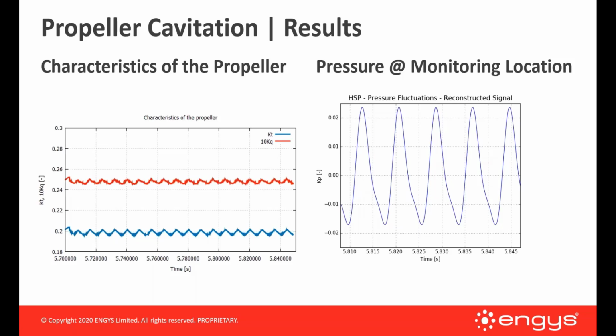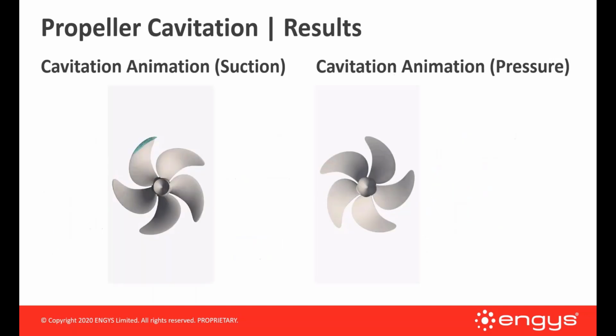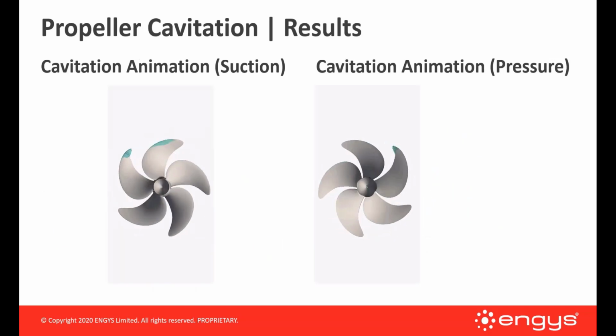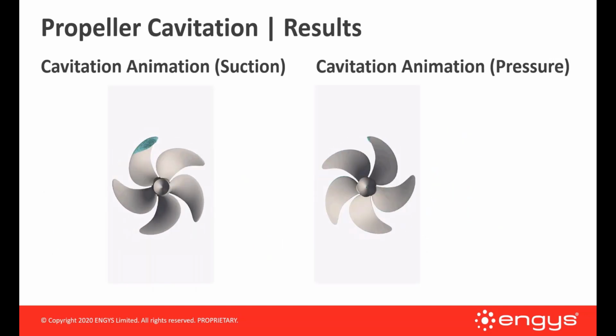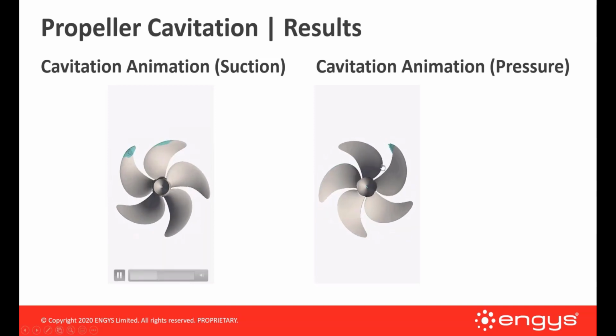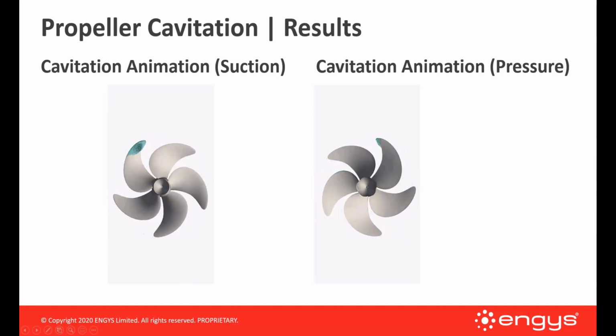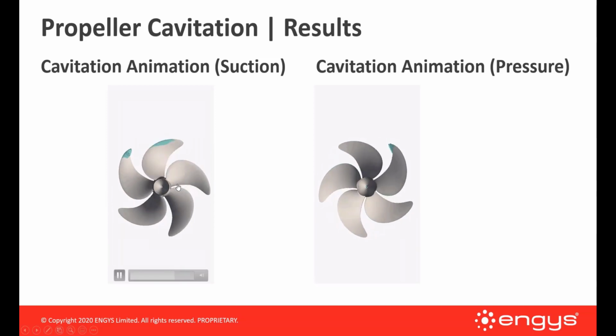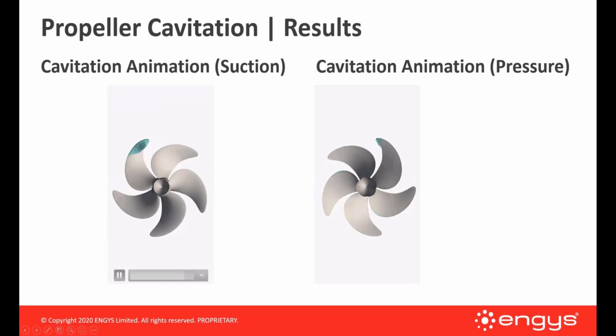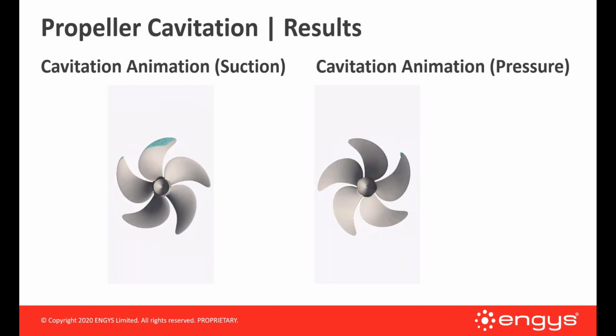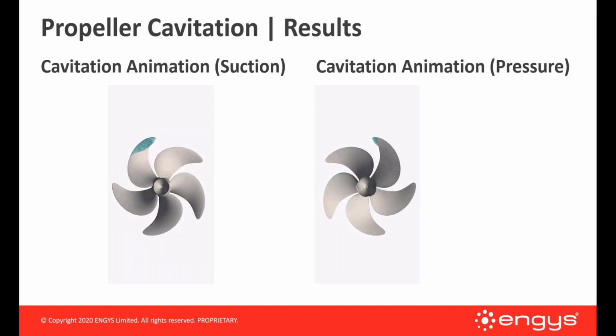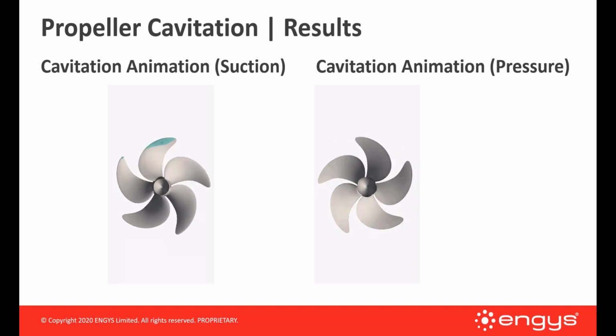So you take the harmonics of a Fourier transform, and you use that for visualizing the filtered data. In terms of cavitation pattern, this is how it looks. This is the suction and the pressure side, and you can see here the effect of the non-uniform axial wake is clearly visible also in the size and the shape of the cavitation pattern.